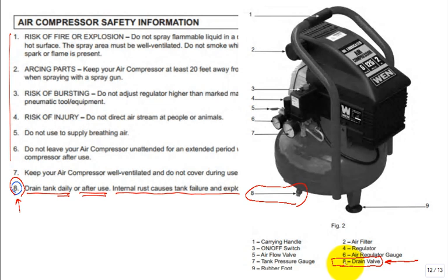And so here's an illustration. And right here on number 8, that's the drain valve. Here's 8. Here is the drain valve. It's sticking off. So you can just go down there, untwist it, keep it unplugged. And then if it's still got some pressure in it, it'll really shoot it out. If you tilt it a little bit to make sure that's the lowest spot, the gravity will make the water go over the surface of that plug, and you'll get some rust-colored, junky water shot out. If it's high pressure, it will spray all over. And if you have pants and other shirts, it'll make it all kind of that reddish. You've done it. I've done it. Many times. Who else has done that? Yeah, okay. See, this class equips you to understand what's going on in your life, right?